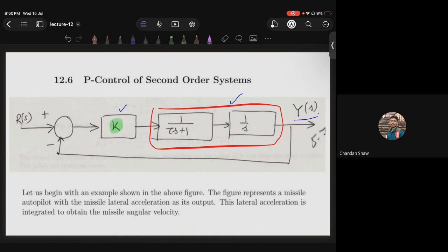Next, what we do is derivative controller. So replace that K with s term. In the integral controller, replace that K with 1 by s. Do the same analysis. So basically this integral controller will remove the steady state error introduced by the proportional controller. Clear? The derivative controller handles the overshoot. It reduces the overshoot introduced by both the integral as well as the proportional controller. Is this clear?